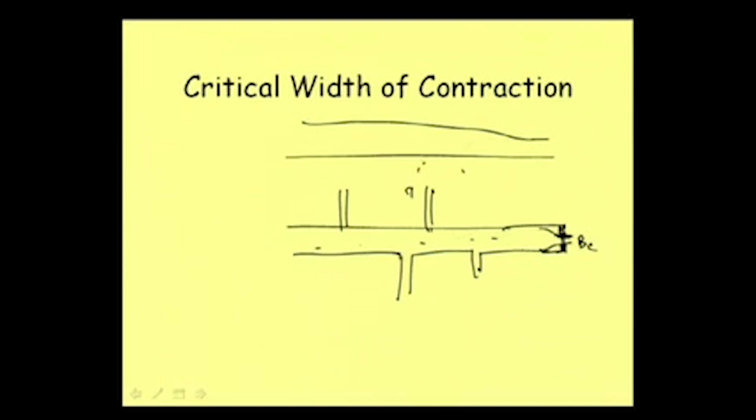Now when the water level is rising in this part, the feeder channels are supplying water to this one drainage. So when the water level here rises, there will be no gradient from this side to that side, because the water level here will be more than the water level there, and this water flow will also stop. That way this part will have drainage congestion.